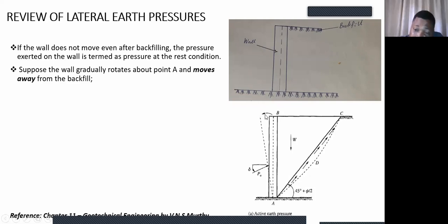If you see the arrow, this arrow will be towards. So this weight of the what? Of backfill is actually the one responsible for moving it away. Because that is very logical to infer that this weight, because a weight is acting at this particular side, horizontally, obviously now, the effect of this weight is going to produce some horizontal forces also, lateral earth pressure. It's going to move this away. Now, moving this away, they are calling it active earth pressure.